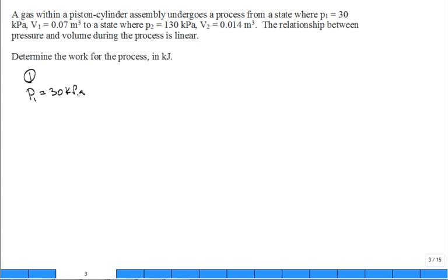What type of pressure is that? It's a low pressure. It's a state of vacuum, actually. Is that absolute pressure, gauge pressure? When it's not explicitly said to be gauge, it's absolute. It's absolute. All right, so this volume 1 is 0.07 meter cubed.